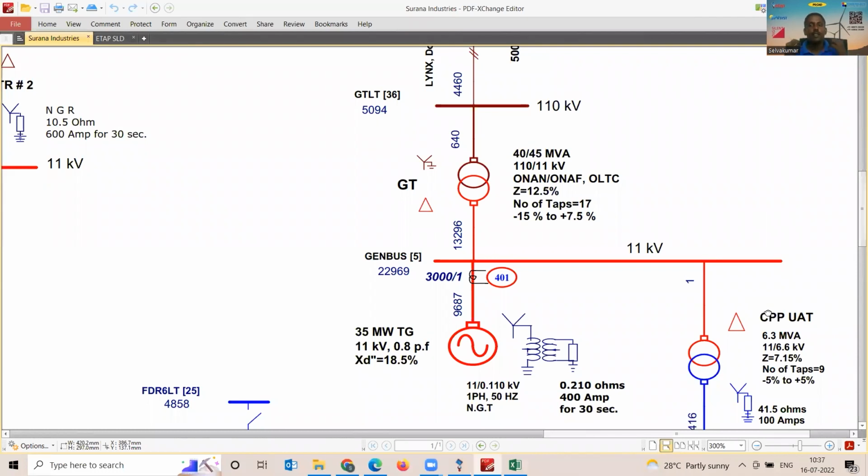Anyway, you need heat for your process industry, which is the steel industry in this case. When you convert electricity into heat, your efficiency will be less than 40%. Similarly, when you convert heat into electricity, the efficiency is again less than 40%. That's the reason why all our thermal power plants typically have an efficiency of less than 40%. Even ultra critical and super critical thermal plants have an efficiency in the range of only 35%.